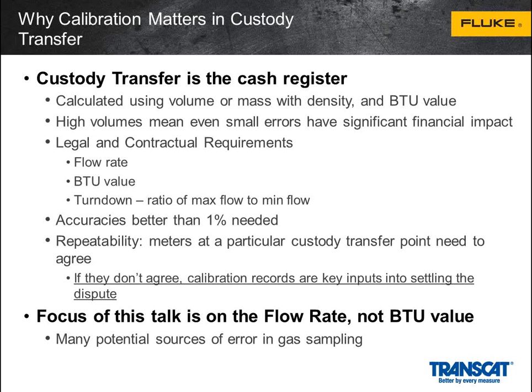Typically, there will be multiple transfer meters at a particular location, and they all need to agree with each other. There will frequently be meter provers installed as well, and if everything doesn't agree, a dispute will arise. What will end up happening is that when that dispute arises, your calibration records are frequently very important inputs into resolving that dispute. Who's right, who's wrong, who pays who owes what. And so the quality of your records matter a great deal, as well as how did you calibrate them? What are the procedures you used? Things like the API standards can help you with the standards portion, but your calibration records are going to be critical inputs.